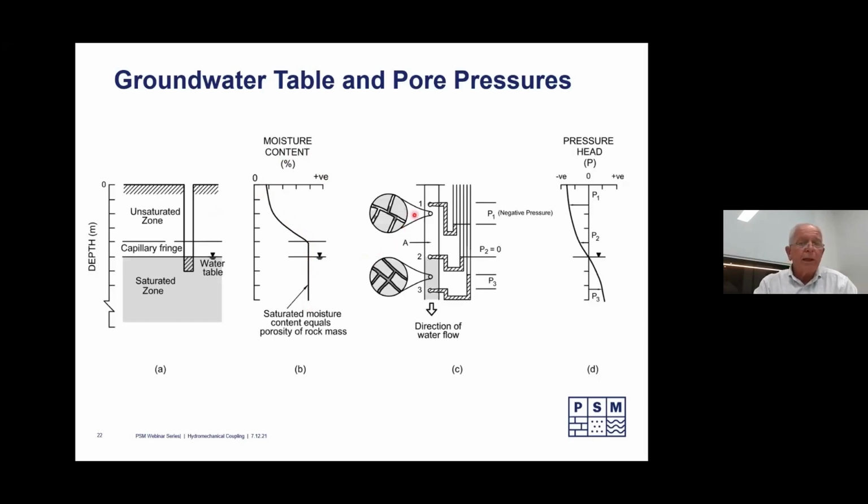That's represented over here again by this tube, which has little tubes that I'm representing as piezometers coming out of it. And you can see here in this little area, we've got some water, the shaded zones in the cracks, but they're not completely filled. And then we go below that and we've got completely filled cracks. And that pressure head then through that profile looks like this. It's negative above the water table and then 0 at the water table and then increasing below that.